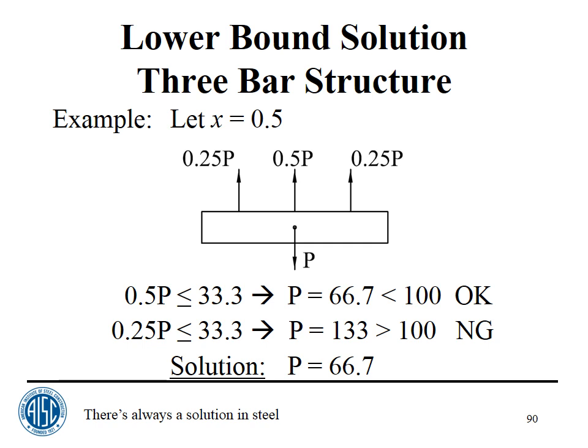So you get, quote unquote, the exact solution or the true solution. But the building is not built like your model says it is. Basically what you've got is a wire diagram with wires that have no cross-sectional dimensions, but they do have embedded properties like area, moments of inertia, radii of gyration, section moduli, shear areas. All of these things are related to wires.